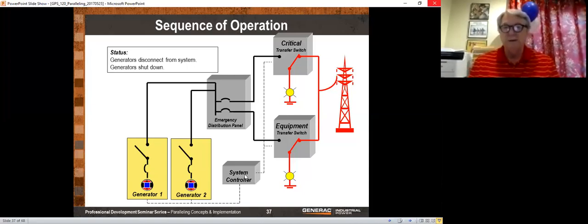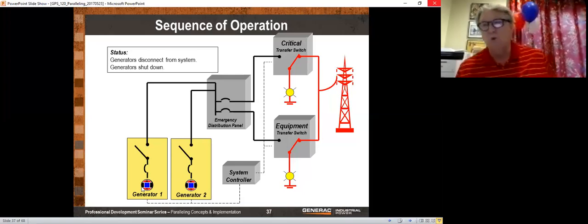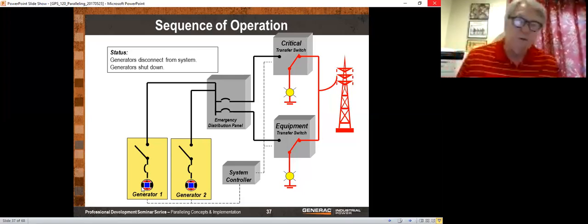And so what I typically do, that's not shown on the diagram, is take this 2-wire start from each of the transfer switches and go ahead and wire it to each of the generators. So this is pretty easy. We just daisy chain, and we take a twisted wire pair from the system controller to the generators, and then we take 3 more wires, although it looks like there should be just 2.